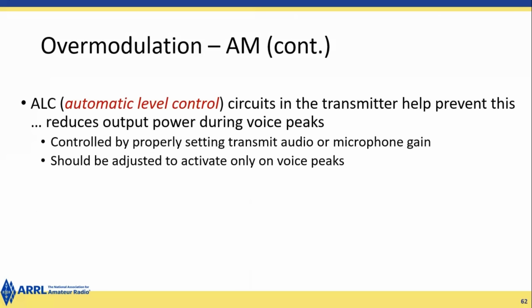An automatic level controller, ALC circuit, in the transmitter helps prevent this type of overmodulation and reduces output power during voice peaks. It's controlled by properly setting the transmitted audio or mic gain and should be adjusted to activate only on your voice peaks.